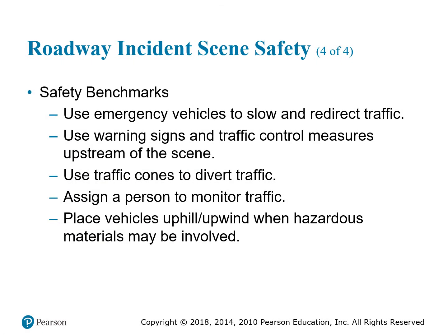Use emergency vehicles to slow down or redirect traffic. Use warning signs and traffic control measures upstream of the scene. Use traffic cones to divert traffic. Assign a person to monitor traffic. Place vehicles uphill and upwind when hazardous materials may be involved.